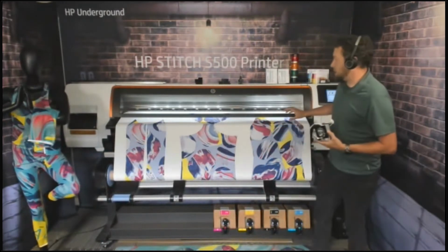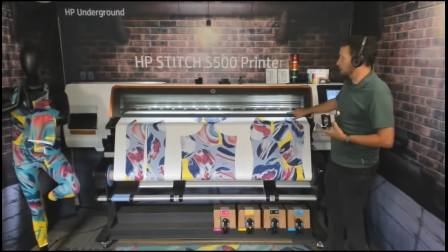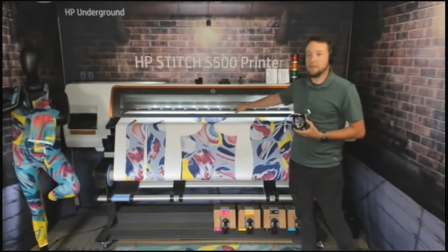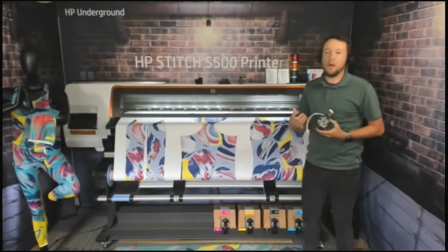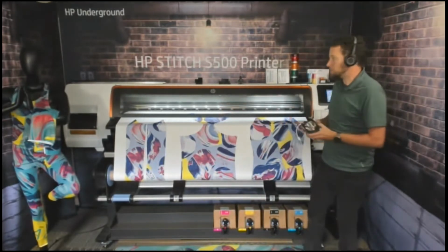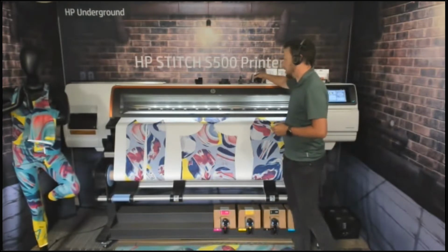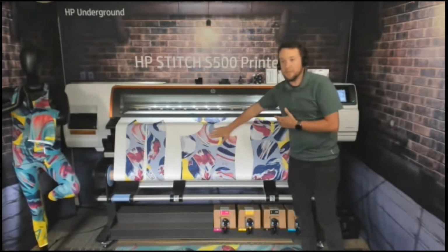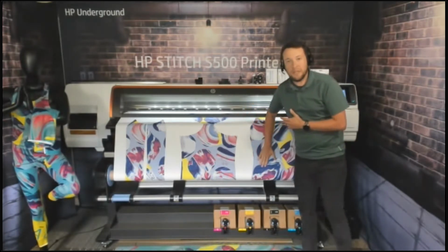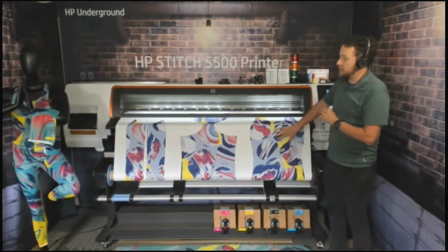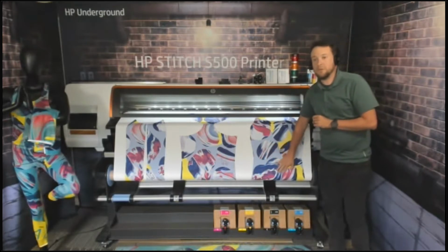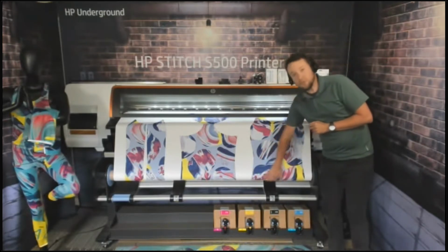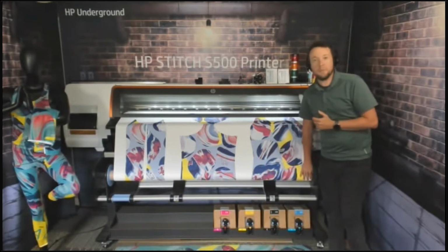So we'll look at this a little bit more in the close-up, but there are diffusers in the back of the print zone where the hot air is being blown out. This allows us to cut down on cockling, and that's where the ink isn't dry before it gets to this part of the take-up. If it's not dry by here and it's still trying to dry, or it's still wet when it gets down here to the actual take-up, it's going to cause take-up issues.